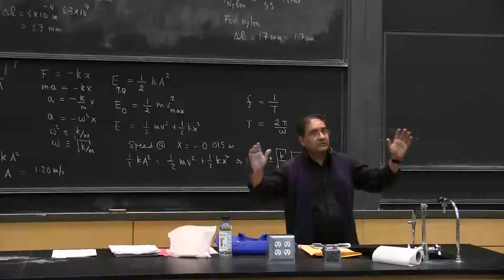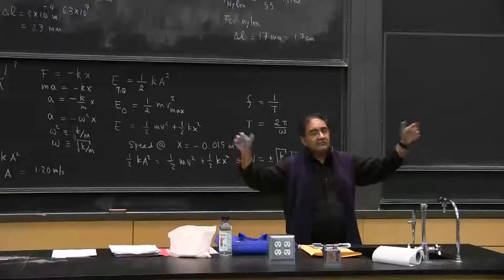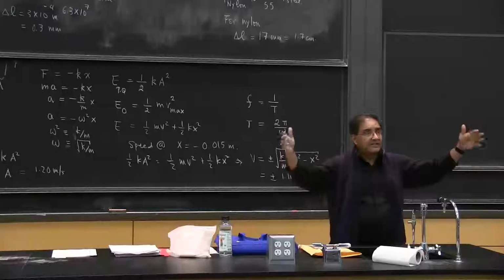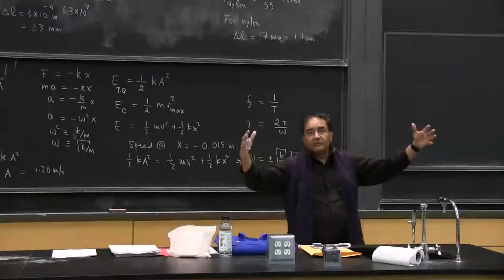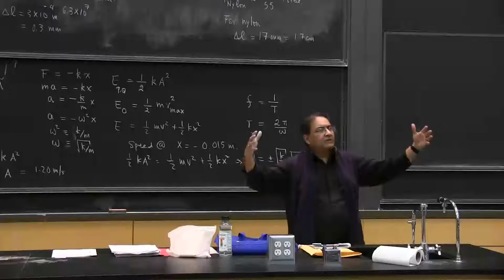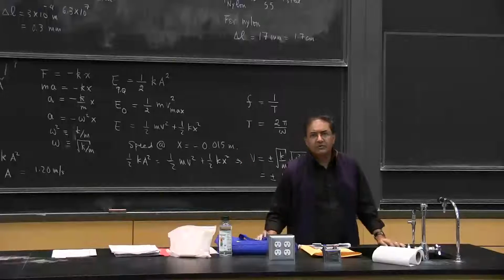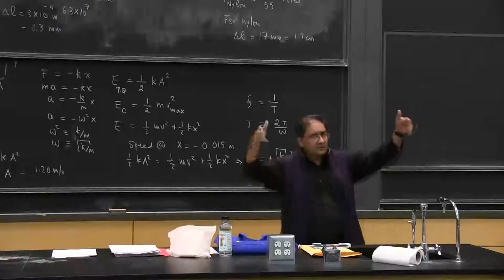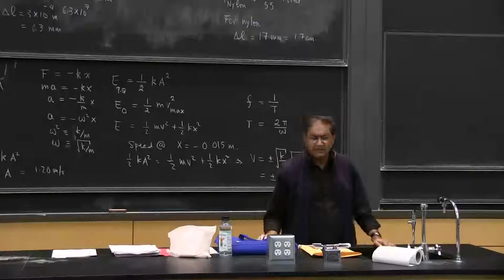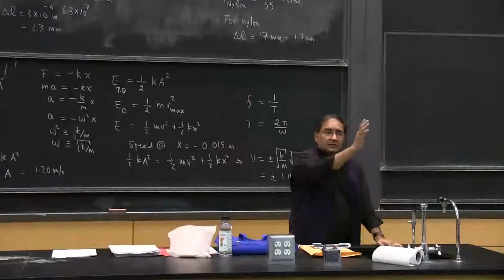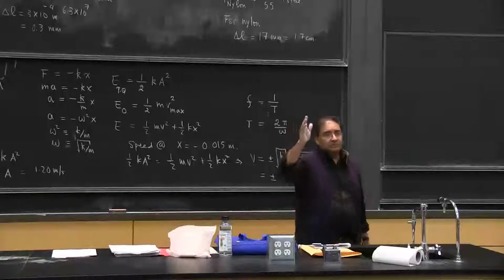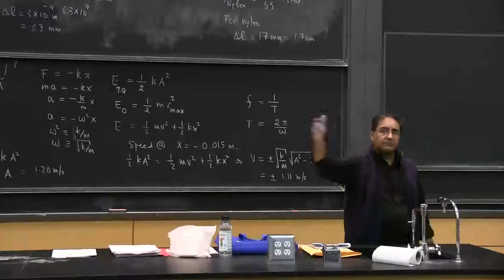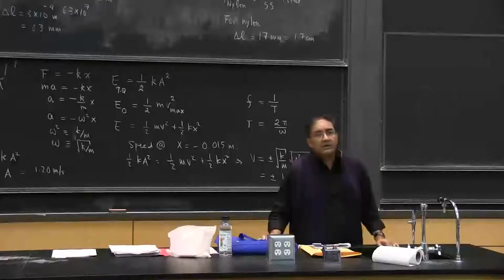So the natural frequency of the whole structure was such that, of course, it had many frequencies, not one, but it had a sensitive frequency at a very low frequency range. And it turned out that they didn't know, this was the 1930s or 40s, I think 30s, that the wind speed in that channel across which the bridge was built, I think this was near Seattle, had a frequency, so the wind would gust at a frequency very close to the bridge frequency. And the entire bridge collapsed. And of course people died. There are pictures of cars falling off and so on.